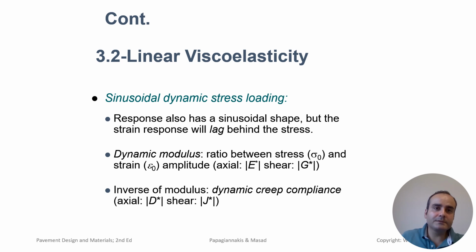Some key concepts in this type of loading: sinusoidal stress is a repetitive wave-like load applied to the material, typically alternating between compressive and tensile forces. The stress is applied in a pattern that resembles a sine wave, with peaks and troughs representing maximum and minimum stress points.